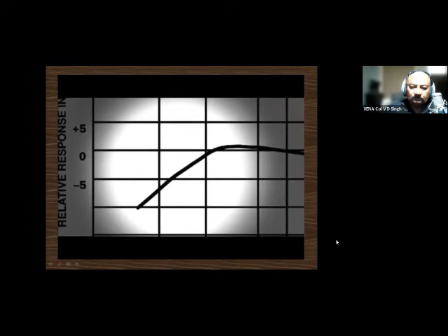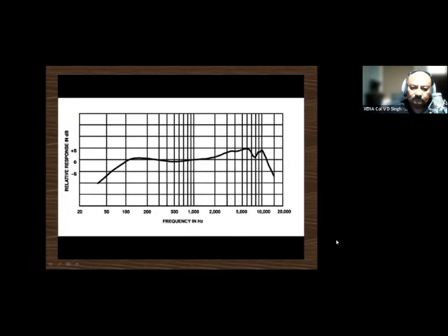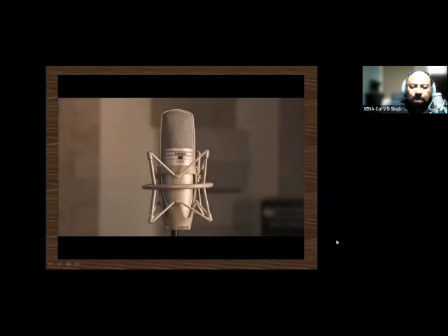A mic with decreased sensitivity to low frequencies reduces pickup of room noise and vibration and counteracts the buildup of bass that can occur when the mic is used very close to the source, which is called proximity effect. The choice of frequency response for miking a particular voice or instrument is very subjective. In general, however, microphones with shaped response work better than flat response mics for vocals.